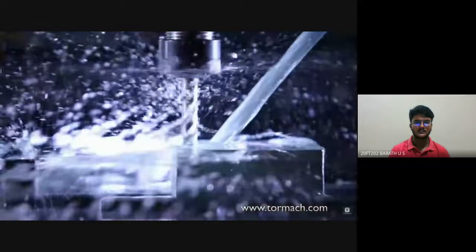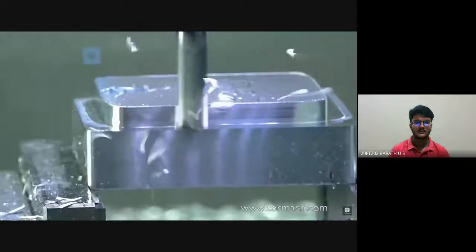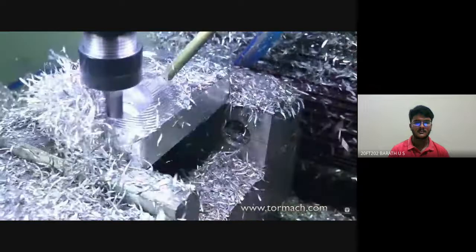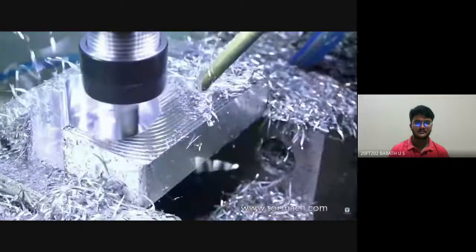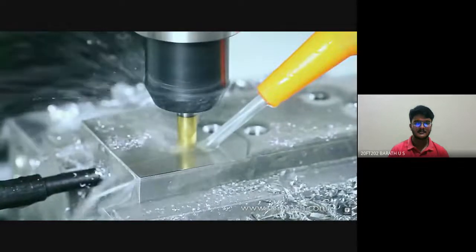So let's mash all these concepts together. Say we're machining aluminum with a high-speed steel cutter. You should flood the part with coolant to keep the tool cool. If we're cutting aluminum with a carbide tool, we can avoid using flood coolant because carbide can withstand the cutting temperatures without excessive wear. You'll still want to use mist coolant with high lubricity to prevent the aluminum from sticking to the tool. Deep pocketing in aluminum with the carbide tool brings up yet another possible configuration. Because we're talking about a pocket, air or mist isn't enough to clear the chips out, though you could get by with it if you needed to. Flood coolant can remedy this situation, keeping both the chips clear and the tool well lubricated.